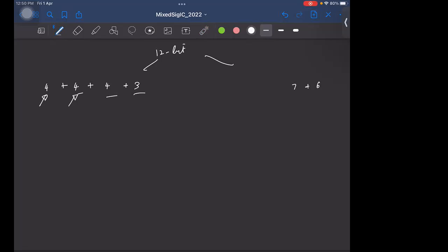Yeah, that is one thing. We'll have more latency here. More stages, we'll have more latency. And also remember that we have 4 stages. How many residue amplifiers do you need here? 3. And each of these residue amplifiers will introduce some gain error, and all of them must be corrected digitally, right? So that's going to add more complexity when you're trying to do digital correction. So probably gain error correction might be tricky here.